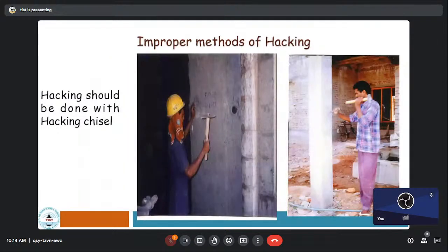And while you want to make some impressions or if you want to cut any structure, what we normally do is hammer and chisel and do more sorts of works. But please understand, it's a masonry structure. It has not attained its strength. So since it has not attained its strength, obviously, it is very, very prone to damage. Am I correct or not?